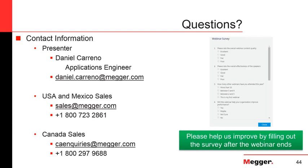In that case, you will have to look at your nameplate and check the rated current for the winding you're testing, and I will mention you have to pay special attention to which winding you're testing, because of course the rated current will be very different from low side to high side. So look at the current of the winding that you are testing and calculate 15% of that, and that will be your maximum current to use.